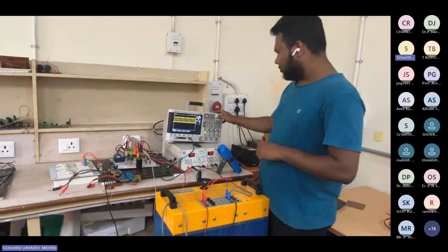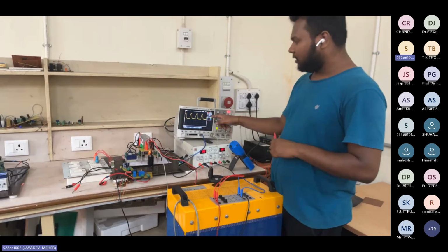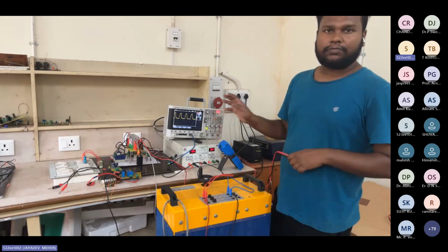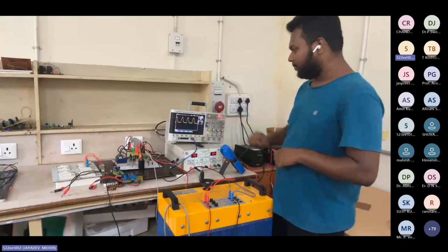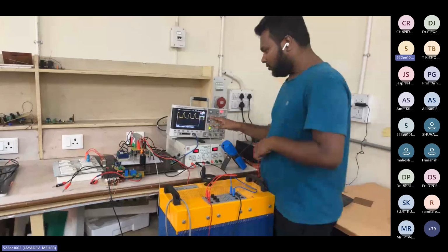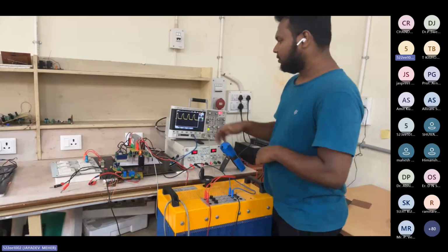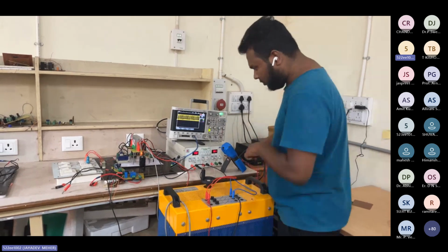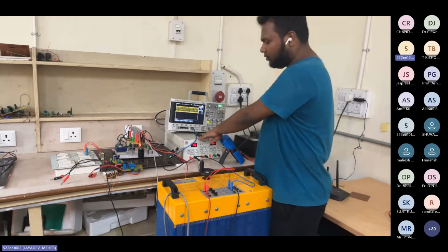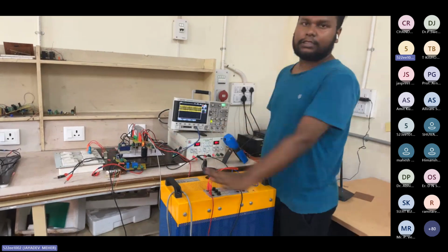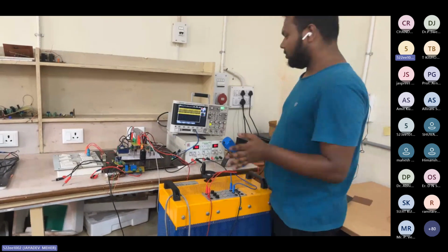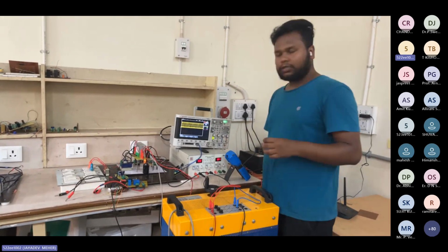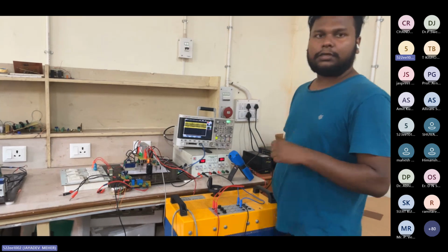You can see that I have built this with a 30% duty ratio implemented and a 20 kilohertz frequency. You can see that duty ratio I put in the gate pulse. This is our power supply, this is the boost converter, and 0.3 is the duty ratio. You know that for the boost converter, V0 equals Vin by 1 minus D.